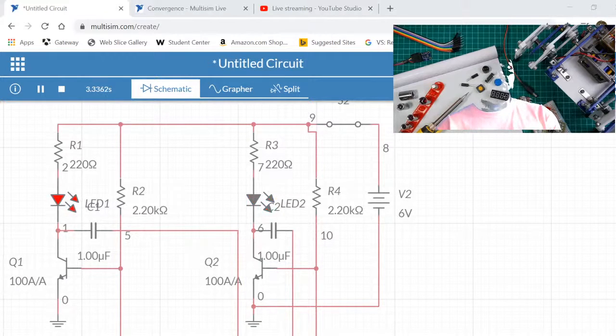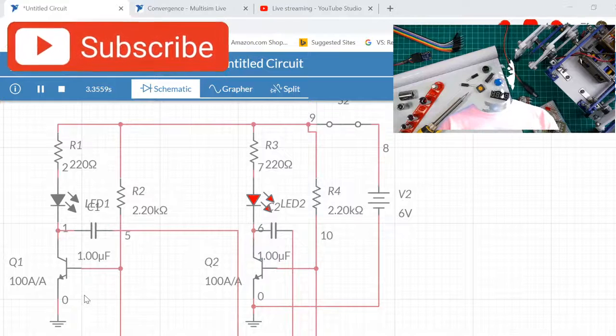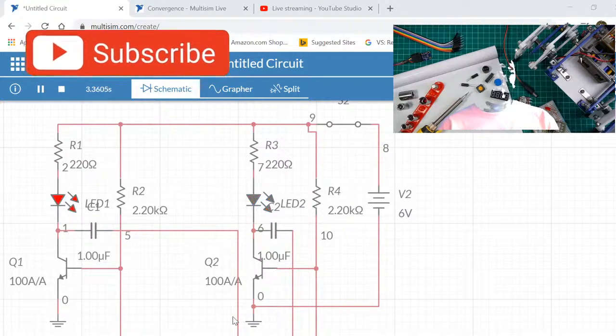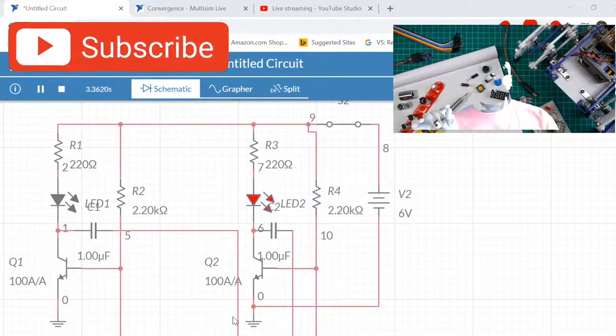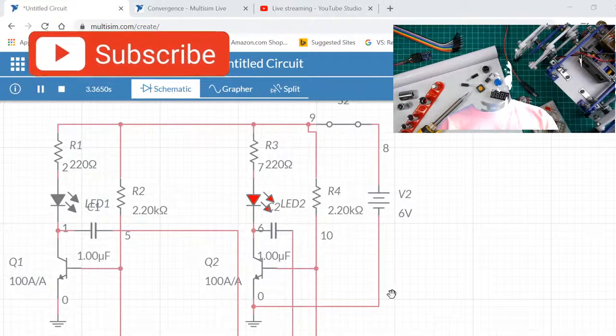So your on time or off time value is basically the same. If they are the same values of resistors and capacitors, then obviously it's going to be the same. But if they are not the same values, take into consideration the resistor tolerances and the capacitor tolerances. Sometimes, even though they are equally rated, the actual absolute value might not be the same.